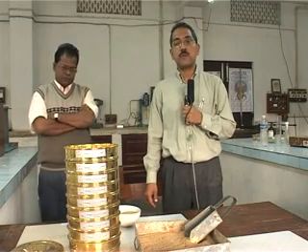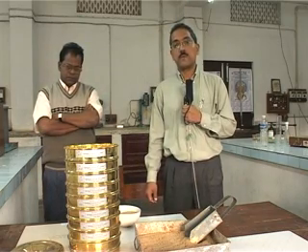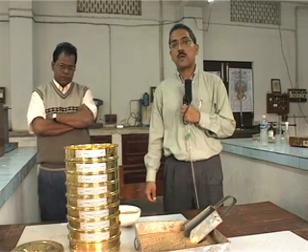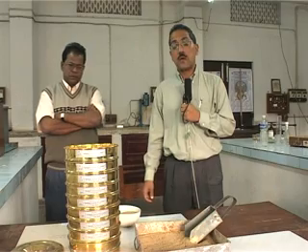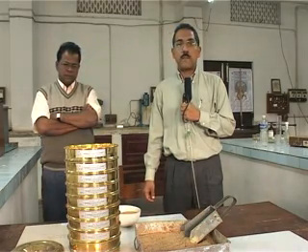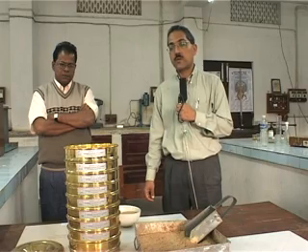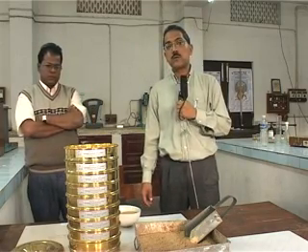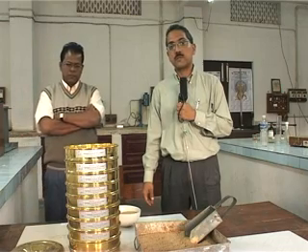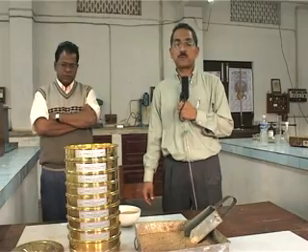Here we are going to give demonstrations on different simple laboratory tests for classification and identification of key soil parameters and rock parameters. With that said, we are going to move on to the first laboratory experiment, involving sieve analysis, which is carried out to find out the distribution of grain size, or the representation of different grain sizes within the soil matrix, for coarse grained soils.